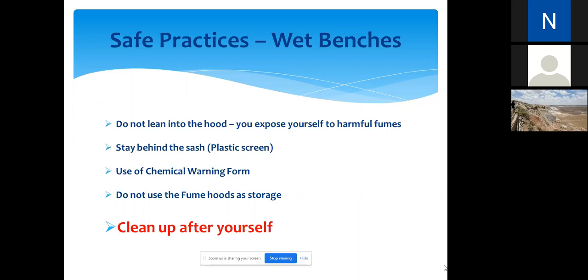Number one. Number two, also remember that you're in the clean room, and what are your contaminants? What is it that's going to contaminate your process? If you are not constantly cleaning, you are adding to the contaminants that are going to haunt you in the future, because you didn't keep your spaces clean, you didn't clean your tables. Therefore, you set down your wafer, and guess what? You just ruined your whole semester's work. So always make sure you clean.